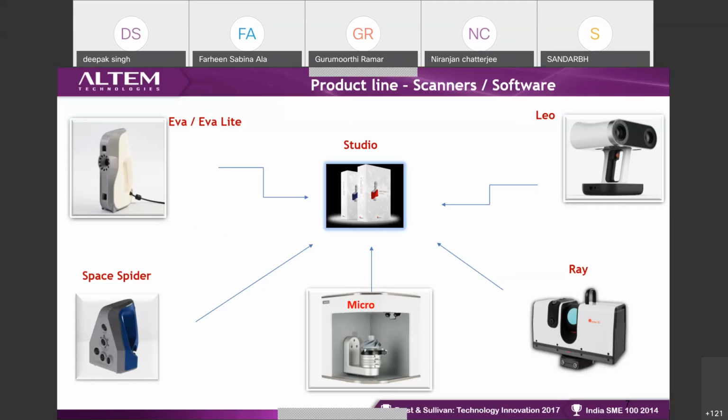The second way is if there is some existing shape you want to print. Suppose you want to print the structure of a hand, or the structure of a human face, a static object that is already there. In that case, we can use this 3D scanner. This 3D scanner basically eliminates the design process. It gives you a file called an STL file. The output of this 3D scanner will be the input for the 3D printing machine. So this will eliminate the process for the designer. What a designer is doing is digitizing the physical shape, and the scanner is doing the same thing.